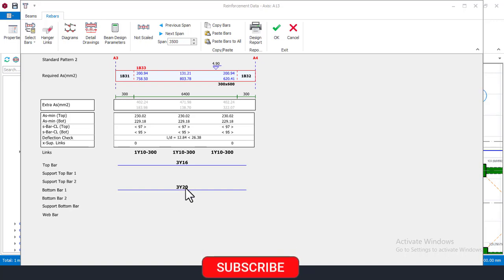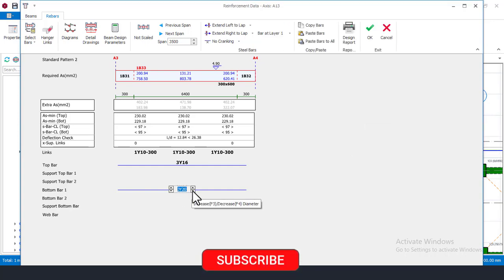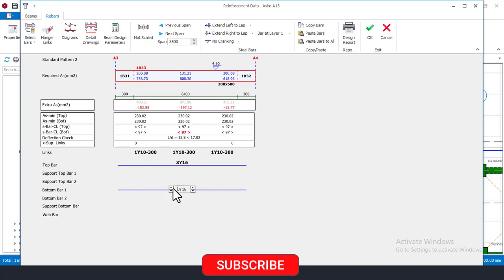So right now I'll try to check if I can use four numbers of Y16 for this, and I'll have to reduce the number of bars here, and there will be a failure. I can see that it is failing right now. I'll have to come here and increase to 4Y16. Once I increase it, basically it's okay, but put your eyes on this place that says extra area of steel. You can see that the area of steel here is showing 3.94, which is very, very minimal, very small.